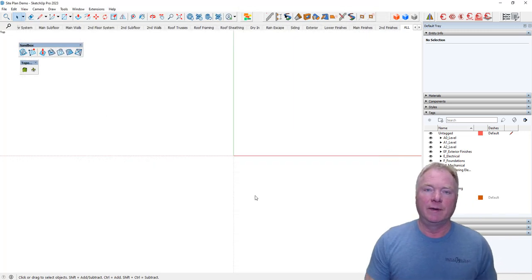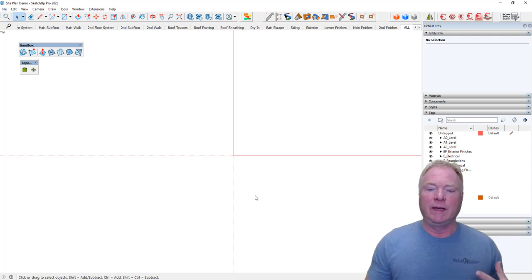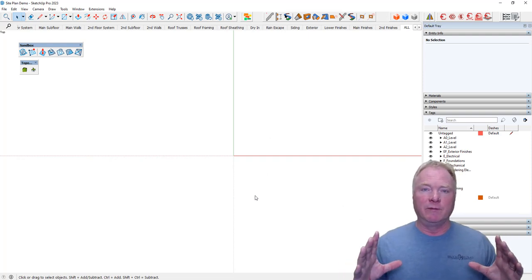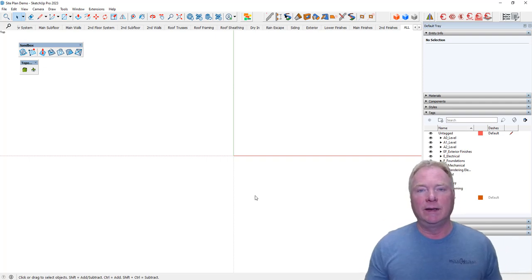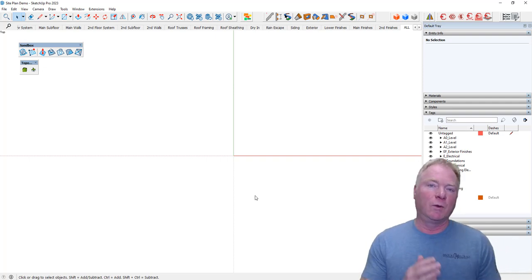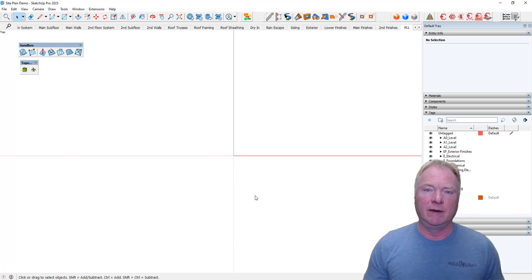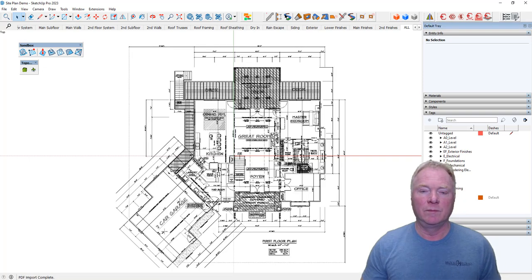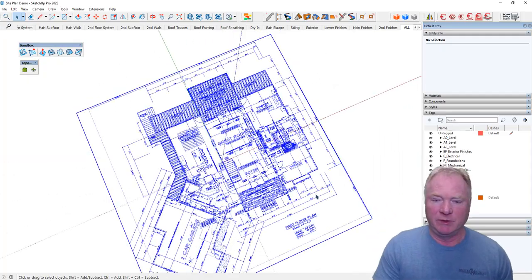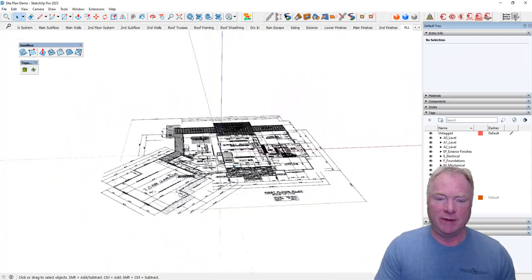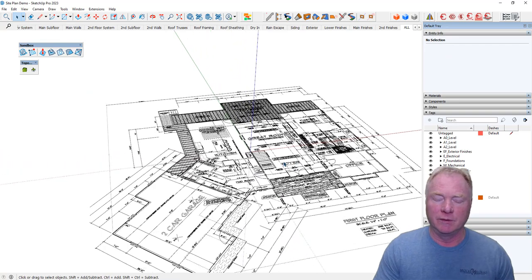the PDF. As this is coming in, the process is I'll start with the main floor, bring that in, make sure it's centered, make sure it's scaled properly, and then we'll do a story pole to then bring in the next level, the lower level, and then the site plan and so forth. Okay, now that this floor plan is in, and you can see it's somewhat centered, I'm going into perspective here and saying, yeah, that looks like it's good on the 000.